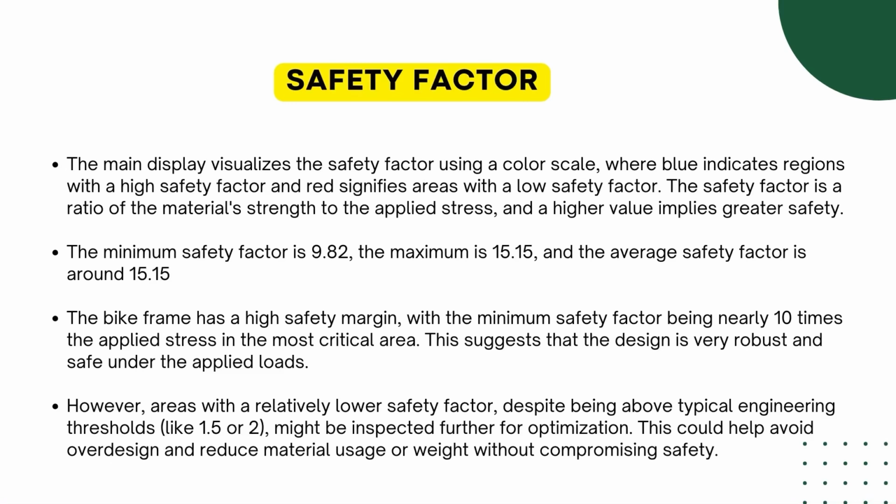The bike frame has a high safety margin, with the minimum safety factor being nearly 10 times the applied stress in the most critical area. This suggests that the design is very robust and safe under the applied loads. However, areas with a relatively lower safety factor, despite being above typical engineering